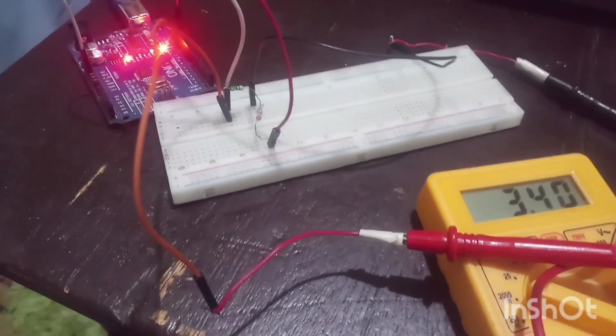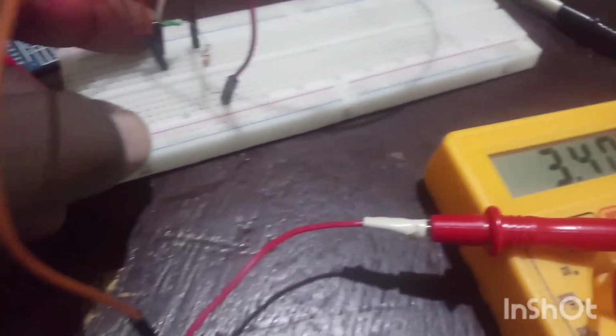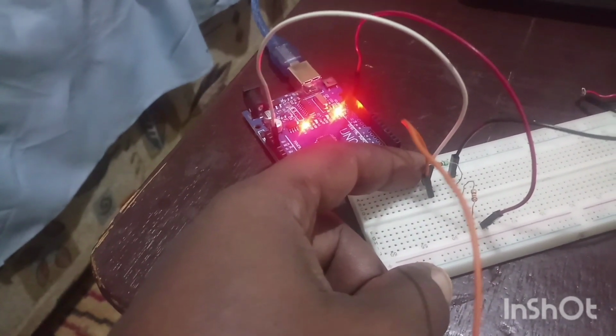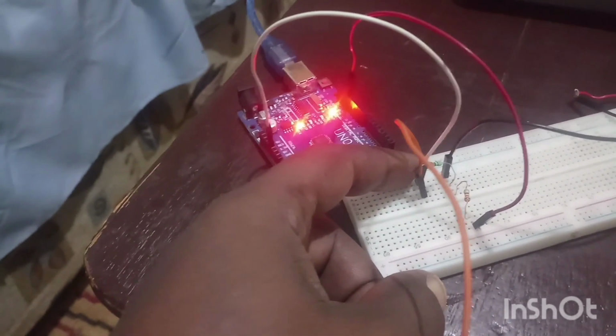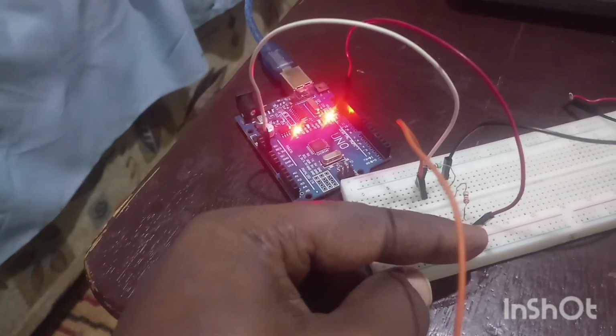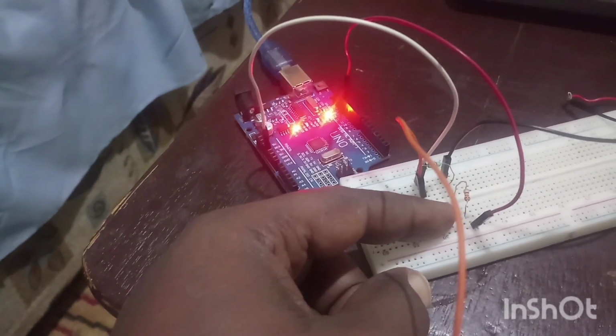1.60 plus 3.40 is 5.00, and we are having 5 volts from the Arduino. It's quite accurate actually. You see what is coming out of that Arduino is 5 volts, and here this resistor is a 450 ohm resistor. That's what I could have, but the recommended one will be 330 or 350. A 330 ohm resistor would be recommended, and maybe something like a 100 ohm resistor. That is perfect for this as well.